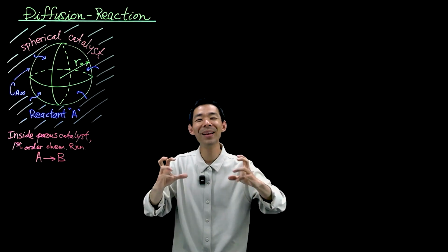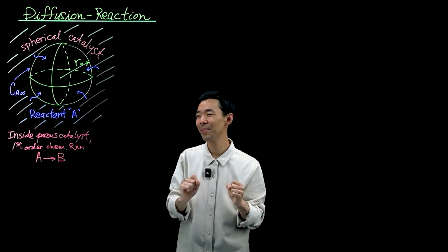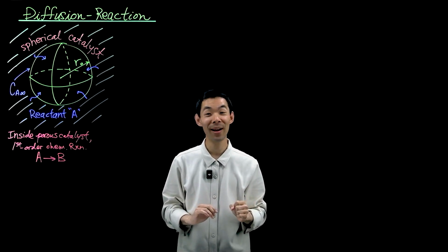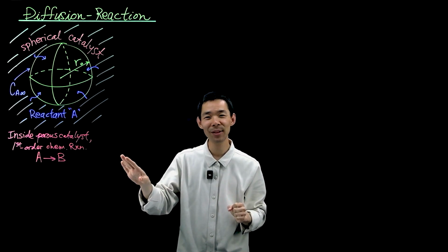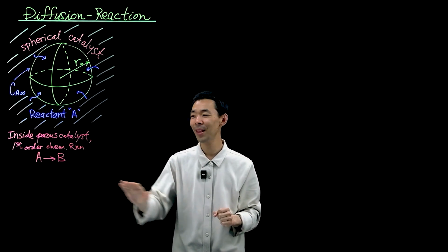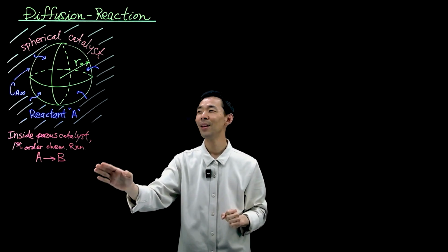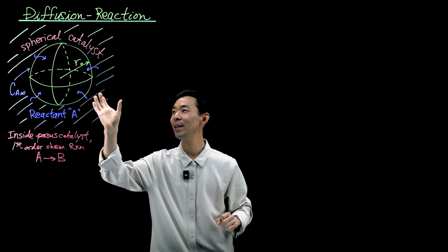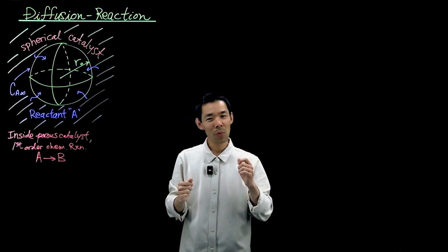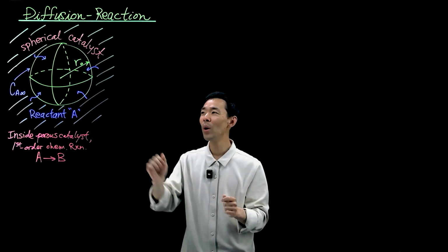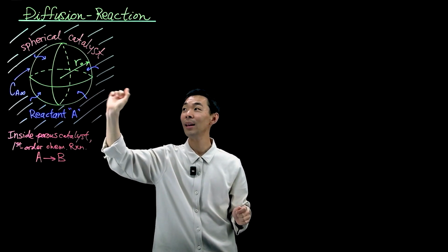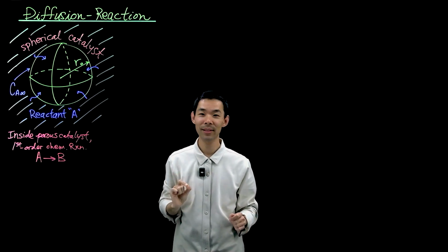And as it penetrates into the catalyst, there is a chemical reaction of reactants going to products. In this particular case, we've chosen a simple first-order irreversible chemical reaction that looks like the following. So there's this chemical reaction happening inside this spherical catalyst. So we want to figure out, what does the concentration of the reactant look like inside this catalyst?